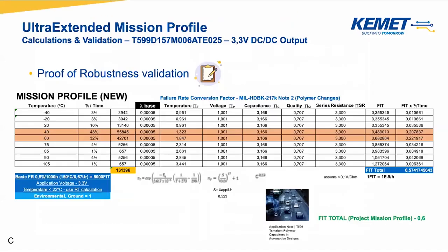And then that's very common in the automotive industry, the mission profile. We get from our customers a mission profile, and then we calculate the FIT rate for each temperature slot, and then we can come up with a total FIT rate and provide it to you, or we can easily provide you a tool that will come up in the engineering center in the near future.